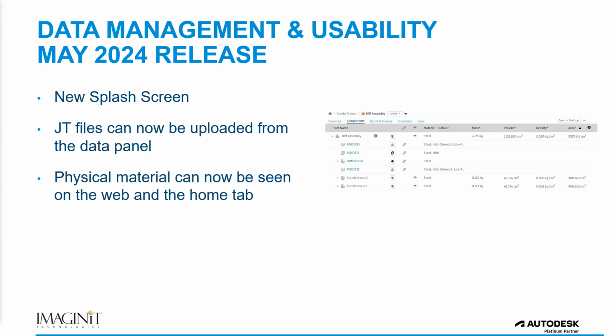So we start again with data management and usability. The first thing you might notice is there's a new splash screen for Fusion. And at the bottom of this splash screen includes a new status bar that tells you what's loading. This is useful in case you get a hang so that you can watch this and see what component is not behaving correctly and see if you can do something about it. It might be an add-in that's acting up. It might be a script that's acting up, or you might need to run the repair tools to reinstall or repair your installation as well.